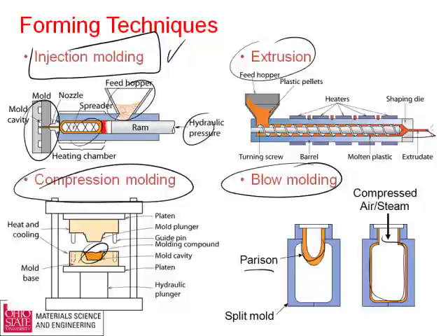Because you've gone from here to here, you've stretched those plastic chains in directions that reduce their entropy. Material likes to be high entropy, so if you go back and heat that up with a hairdryer, it'll tend to go back, not exactly, but towards that parison shape, and that's that shrinky-dink effect that I keep talking about.